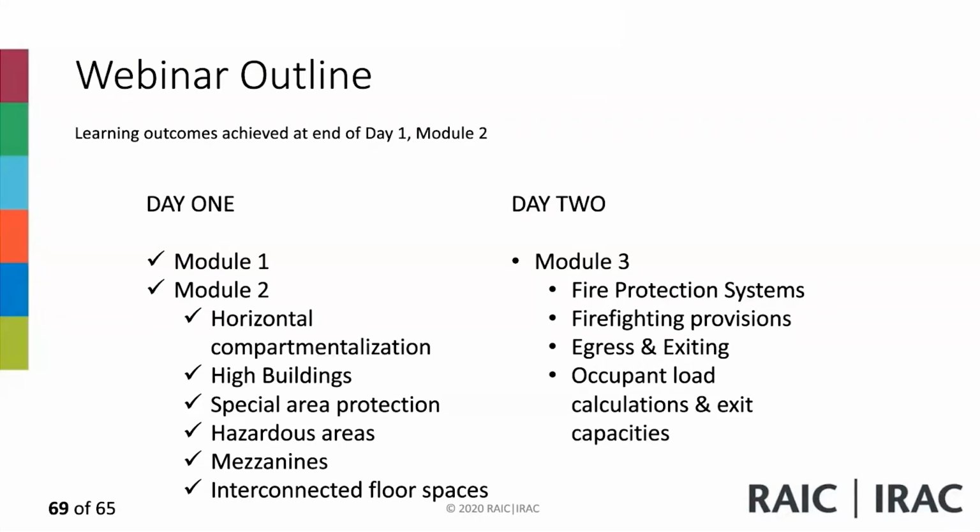But if you have another level superimposed onto that first level of mezzanine, it's considered a story, in which case it's considered a fire separation. In this case, you want to rule out that it's used as a platform with no storage, or that it's used as a mezzanine, if it's not more than 10% of the floor area. So depending on the area, you can still look at it as a mezzanine that's no more than 10%.